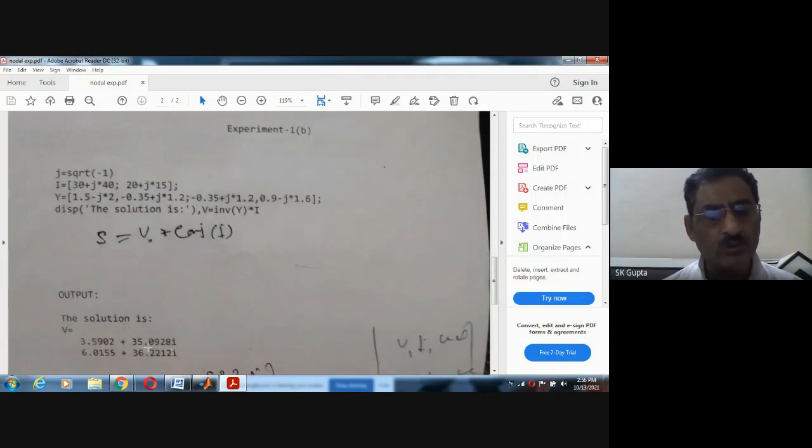So you know this voltage, you know this current. Then if you multiply this V into, suppose you write conj of I, it understands, as I told you, MATLAB understands conj means conjugate of I. As soon as you do this, it will make its conjugate. Conjugate of I means plus becomes minus and minus becomes plus, and it makes the conjugate. So it will give the conjugate. The cross means multiply.